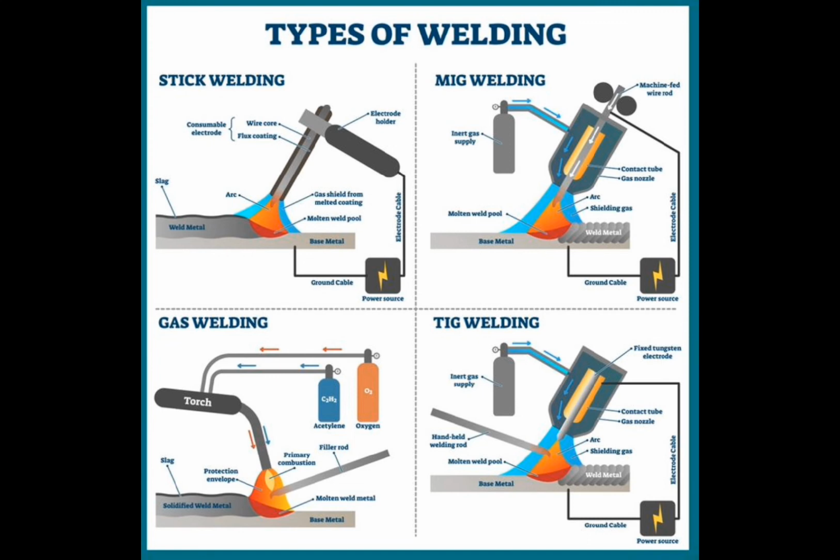What is the maximum safe pressure for acetylene gas when welding? 15 psi. No greater than 15 psi. What is the function of flux when used in soldering? Removes oxides and prevents formation of new oxides, so the solder forms a strong bond. Flux removes corrosion from the surface.